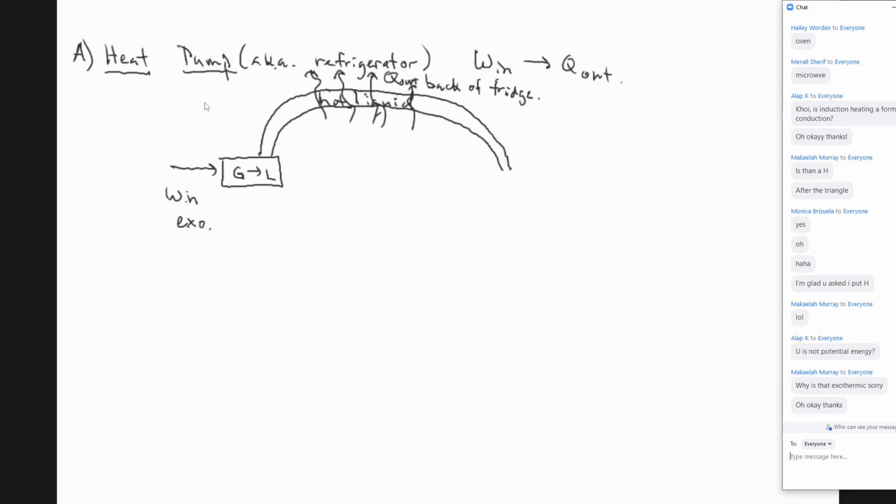So if it's too close to the back of the wall or it's touching the wall, it could possibly heat the wall, over time drying your wood, over time causing that wood to catch on fire. So in an effort to save room, don't push your refrigerator all the way to the back. Make sure it's about an inch to 3 inches out from the wall.